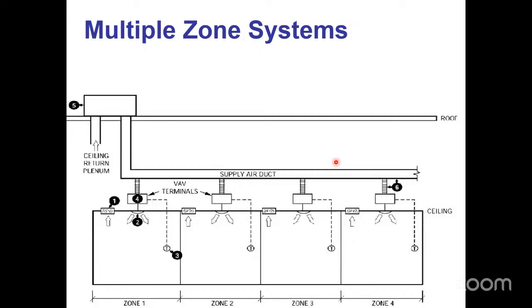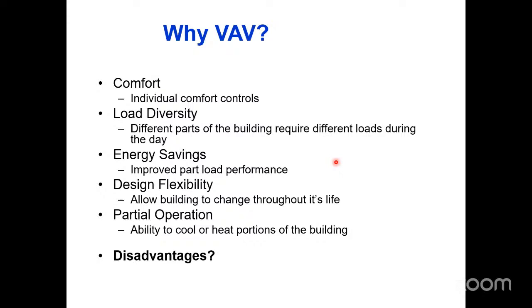But if I have a constant volume system, I'd have to get a 60-ton unit. Well, by having a VAV system, I am allowed to take diversity into equation, which for rough discussion means that my air handler should be about 80% as big as it would be on a non-VAV system. So instead of 60 tons, I should have picked easier math. Instead of 60 tons, it would in fact be a 48-ton system. It's not always exactly 20% smaller. It just depends on the way the loads are, but you can look at the individual loads and what time of day and year they peak.